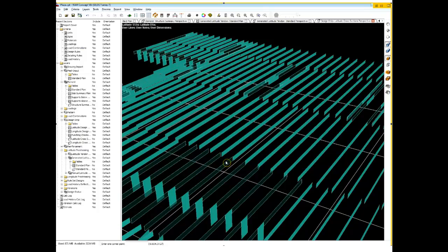Now, some cross sections are going to be solid here. That's the critical design area. Some will have a solid portion, and then what looks more like a hollowed out portion. Only the solid portion is used for the critical section dimensions in your design strip calculations.